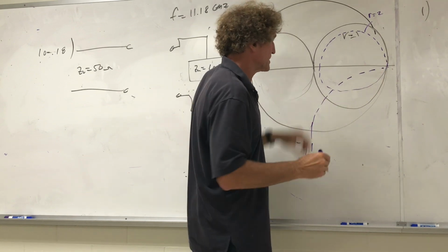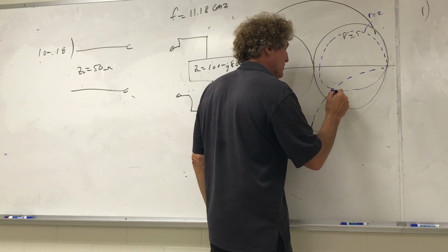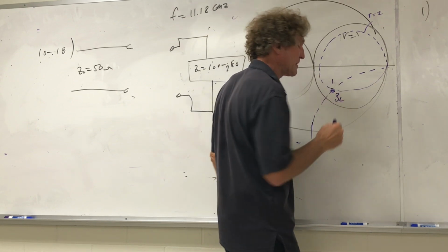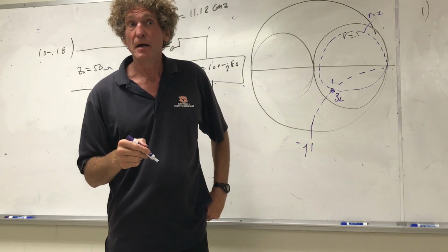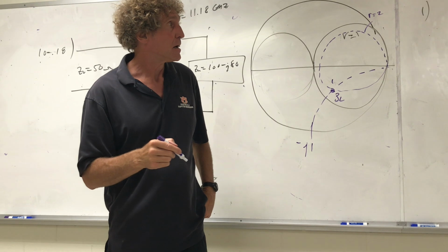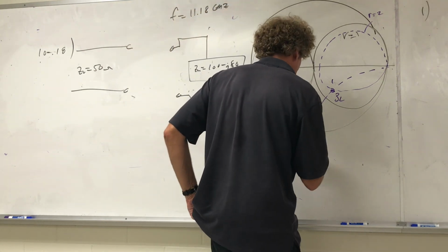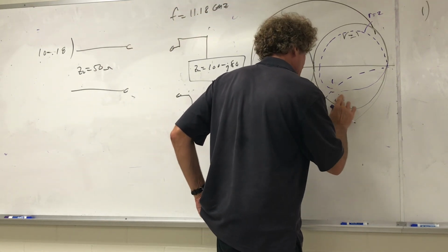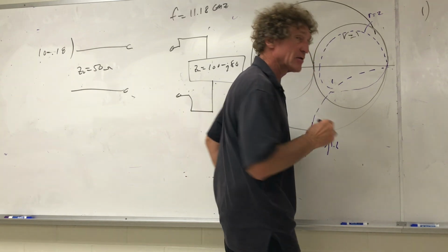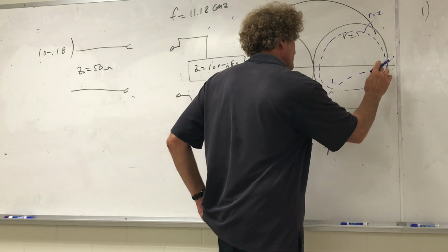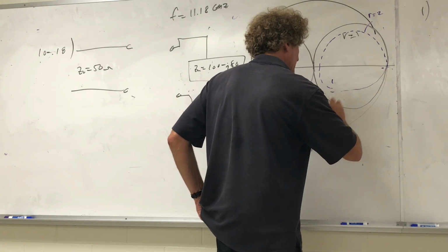Now take a look at your Smith chart. So this would be the point. It would be point 1, it would be zL. Can everybody find that? You have your Smith chart? Wow, it'd be minus. Oh, 1.6, 1.6, sorry. This is minus j1.6, I'm so sorry. It's very close to straight north now. But it should be like this.